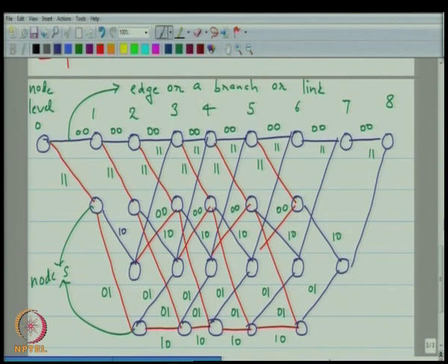Okay. So, now I have all my branches labeled with outputs as well, and repeating the same argument, but this time with a focus on the output sequence, you will see that if the input message sequence is all 0, the output sequence is all 0 as well. If the input message sequence is all 1, which means you follow all ones except the last two being zeros, then the corresponding output sequence you can read off on the trellis.